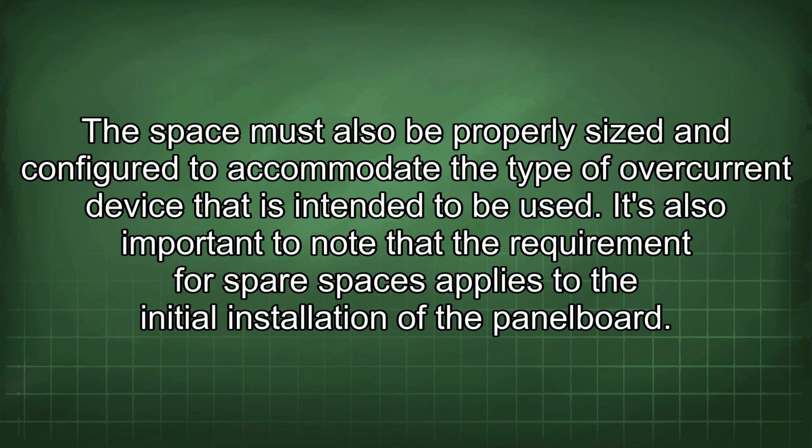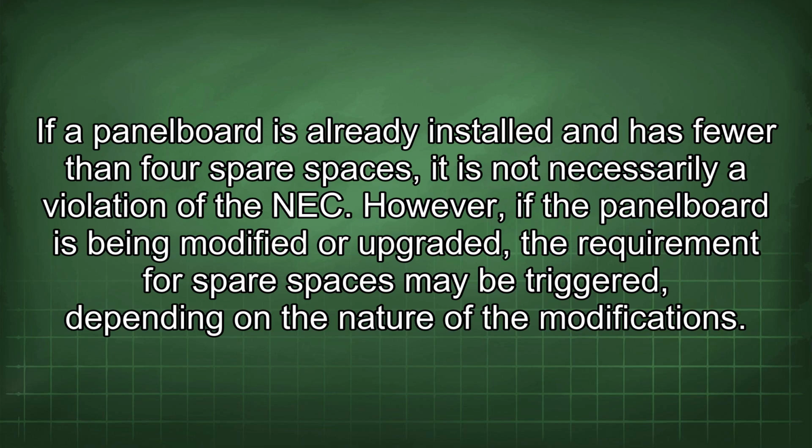It's also important to note that the requirement for spare spaces applies to the initial installation of the panel board. If a panel board is already installed and has fewer than 4 spare spaces, it is not necessarily a violation of the NEC. However, if the panel board is being modified or upgraded, the requirement for spare spaces may be triggered, depending on the nature of the modifications.